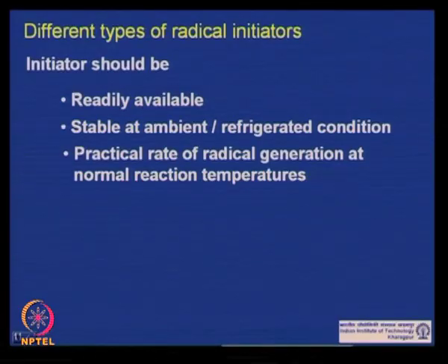And the third one, as we just talked about, is that it should generate radicals at a practical rate at normal reaction temperature. It should not be too slow, so that the reaction takes much longer, or too fast, since there are possibilities of hazard because of exothermic reactions happening at a much faster rate.